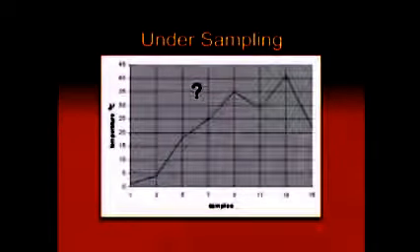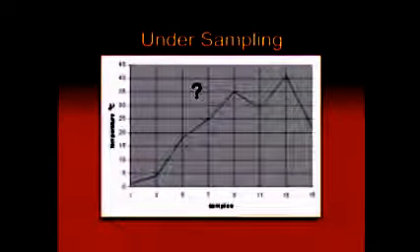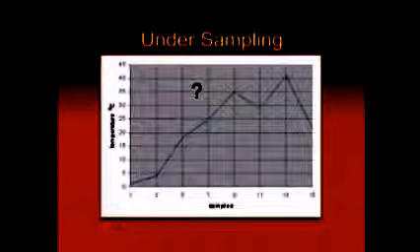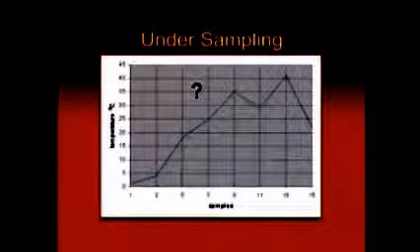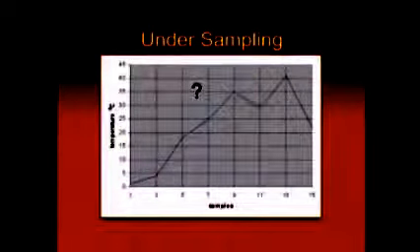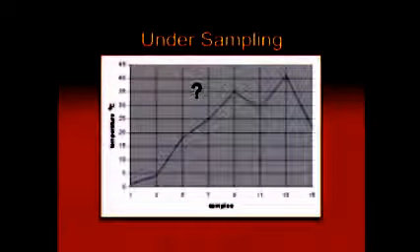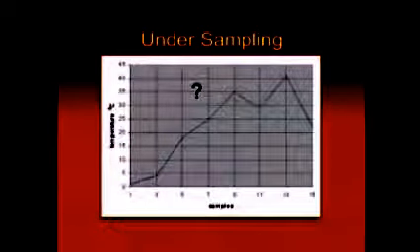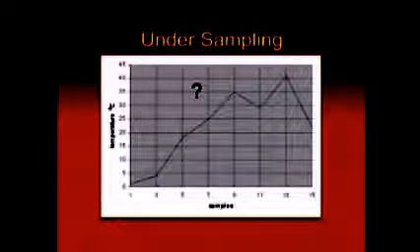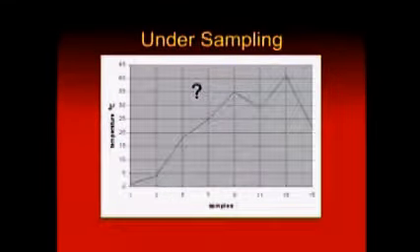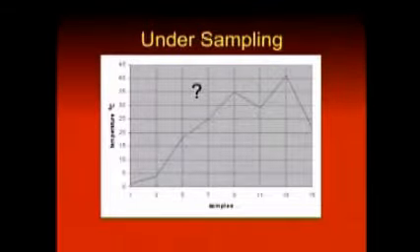The peak in the continuous signal at 34 degrees centigrade and the dip at 23 degrees centigrade are altogether missing from the reconstructed signal. This is due to the small number of samples taken. A better approximation of the original signal can be obtained by increasing the number of samples. An infinite number of samples very accurately represent the original continuous signal.